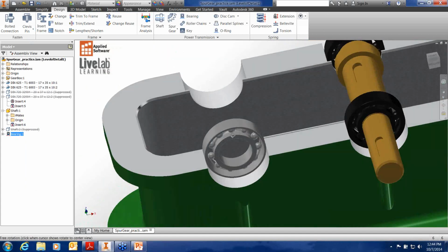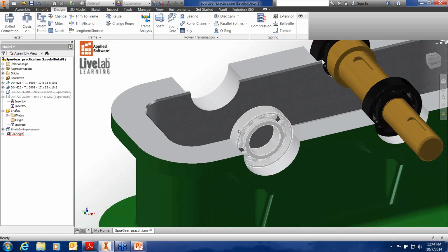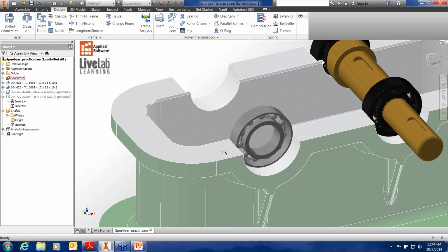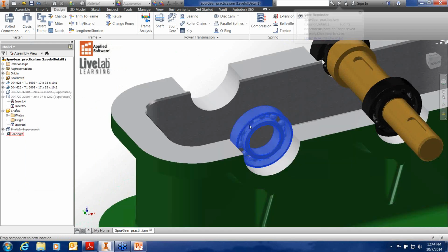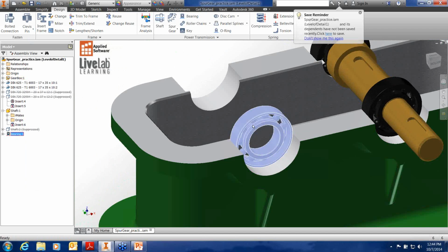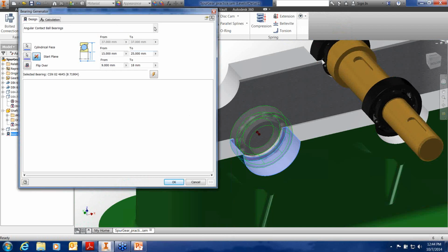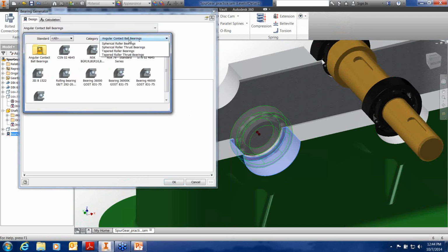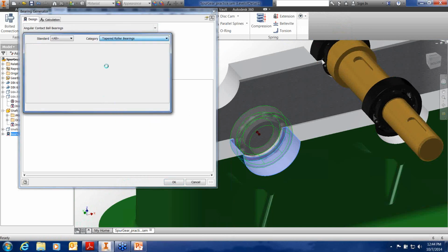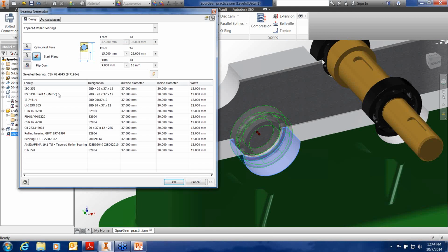Now at this point, it is associated to the part and to the housing here, and so it is locked down. It will not move. It spins, but it will not move out of that location. I can again right-click on it. Maybe this time instead I might want to change its style a little bit. I could go down to, for instance, a taper rolling, give myself a selection here. It remembers all the settings here, if you'll notice.